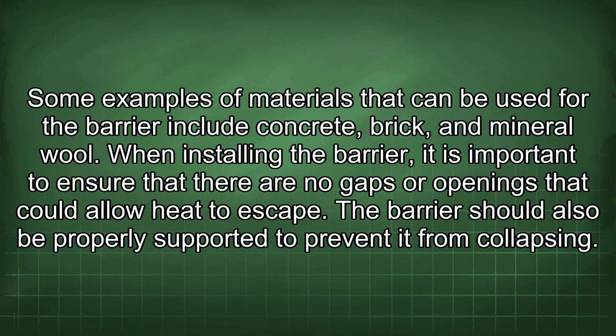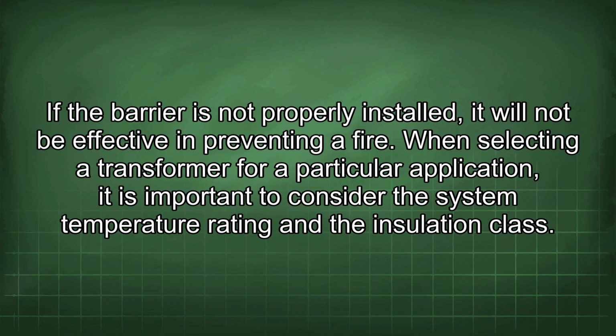When installing the barrier, it is important to ensure that there are no gaps or openings that could allow heat to escape. The barrier should also be properly supported to prevent it from collapsing. If the barrier is not properly installed, it will not be effective in preventing a fire.